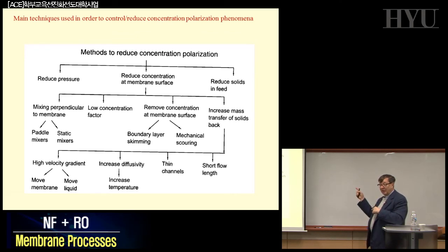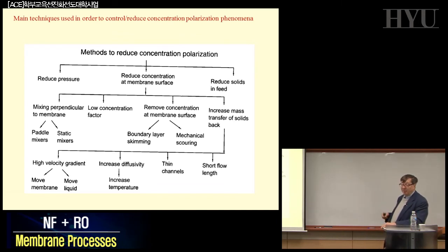Because the equation that I wrote down said flux is proportional to the driving force. So if I increase the driving force, I increase the pressure. But the driving force is not ΔP. It's ΔP minus Δπ. And so for any reason you increase Δπ, the system doesn't know. But this is a little bit more sophisticated than just saying proportional to ΔP. So you have to understand what concentration polarization is. So this is one way.